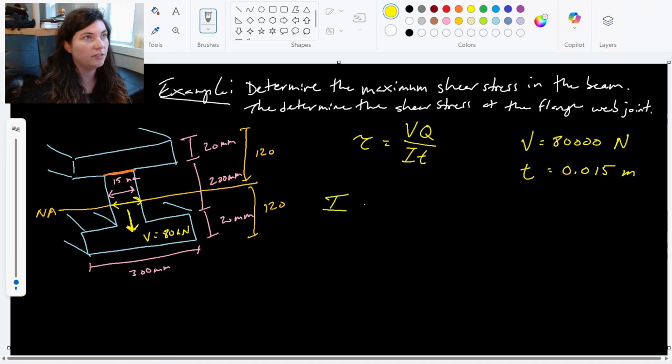Remember, you recall from statics, it's I_x plus A d squared. Since we're working with a composite shape and they're all rectangles, you'll sometimes see me rewrite this as the sum of 1/12 base height cubed plus A d squared.